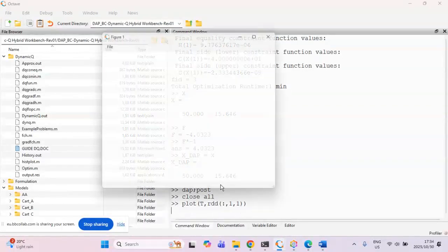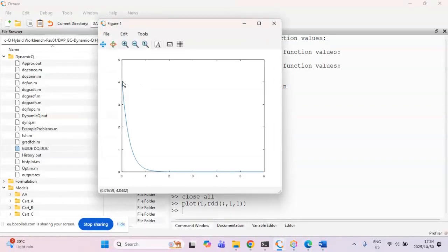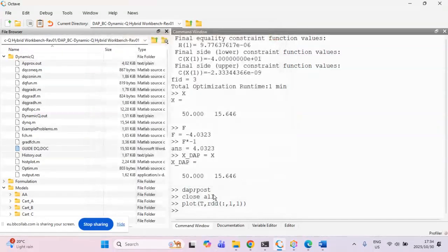And I can just close the brackets, hit enter, and over here I can see that I now have the maximum acceleration of 4.03 where I start off, and then at around 2 seconds it seems that I've now plateaued at a value of 0, so now I don't have any acceleration in the system. So this tells me that I should see a constant speed when considering the motion of the kart body itself, and therefore I can now go and just retype or hit the up arrow on my keyboard, and now I can consider the x velocity of the kart as well.